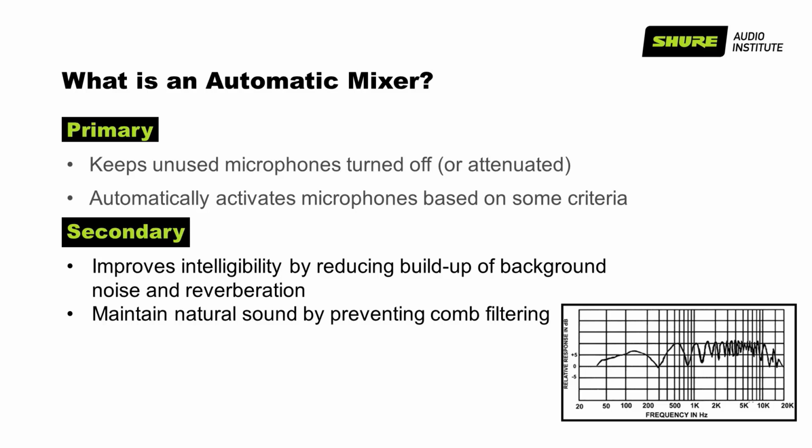Yeah, I would say that anytime you have an application where there's more than 2 microphones, you should be using an automatic mixer. So people ask, how many microphones do I need? What if I only have 2 or 3? Really, any speech application, it's worth having one of these in there. And again, they're seamless. You don't miss words. If it's a good auto mixer, which most of them are pretty good these days, you don't miss words. You don't even realize it's doing anything until someone turns it off, and then suddenly you'd have 8 live microphones, and you'd be like, well, what's going on here?